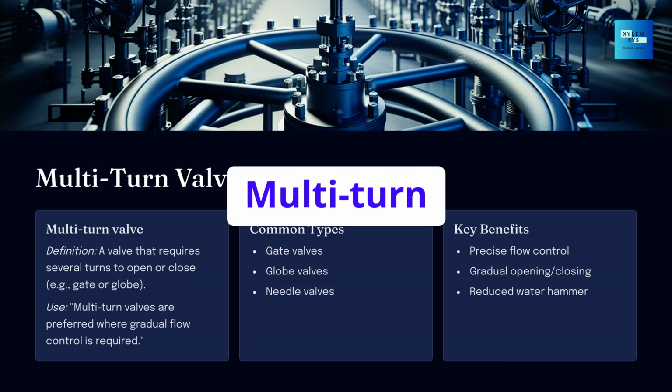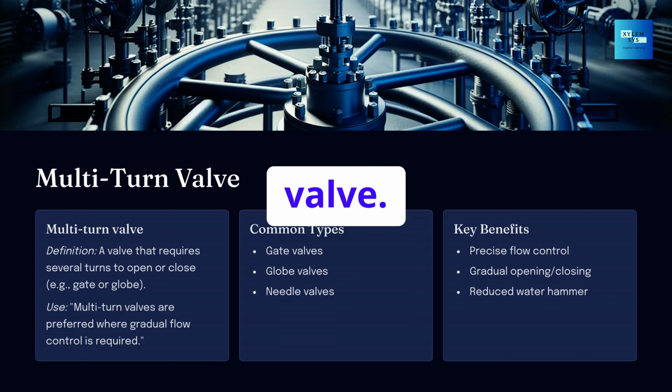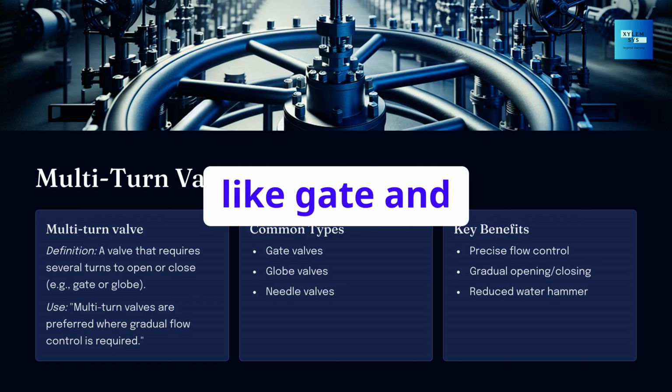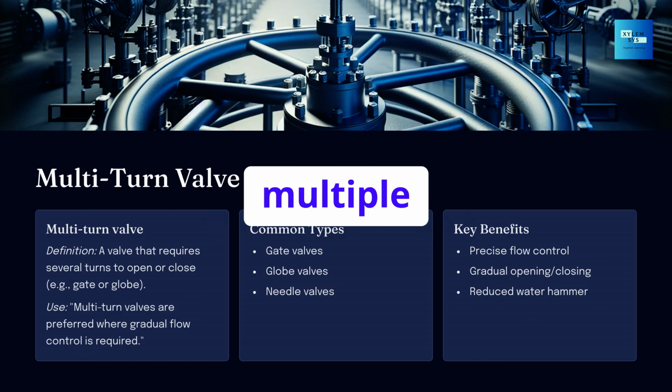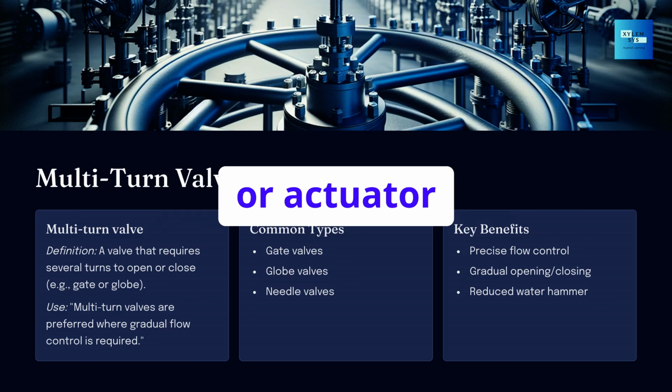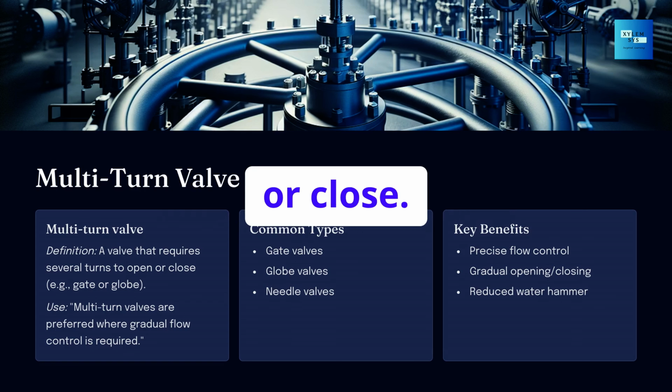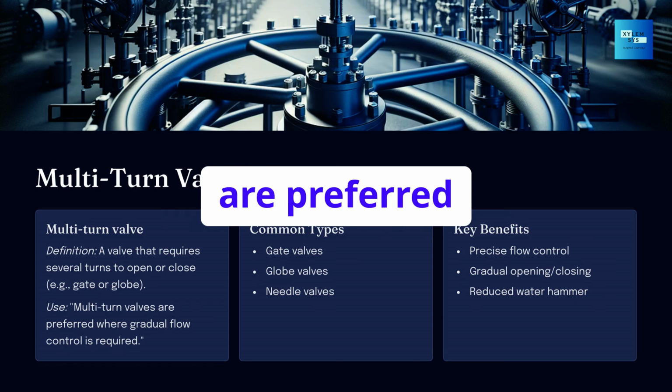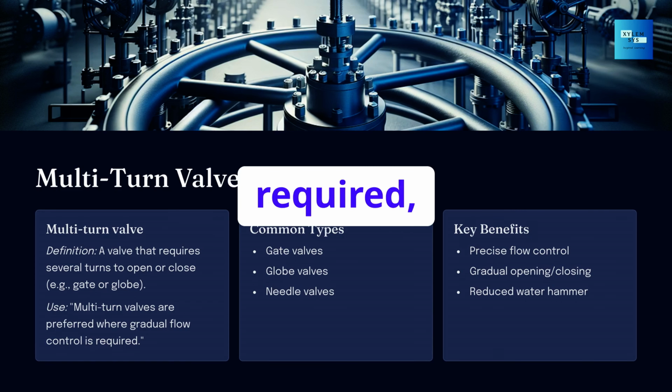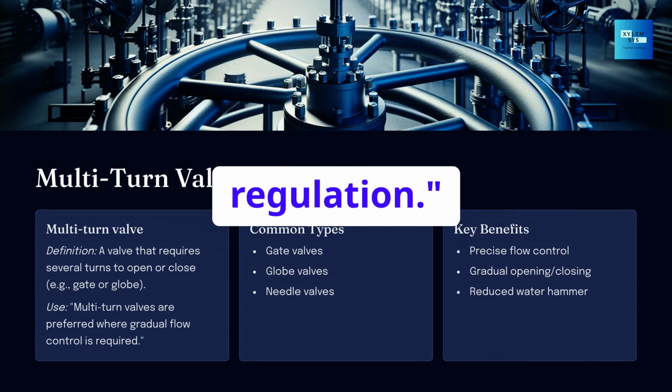20. Multi-turn valve. Multi-turn valves, like gate and globe valves, require multiple revolutions of the hand wheel or actuator to open or close. They offer fine flow control. Multi-turn valves are preferred where gradual flow control is required, such as in cooling water regulation.